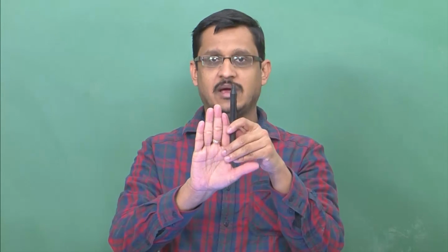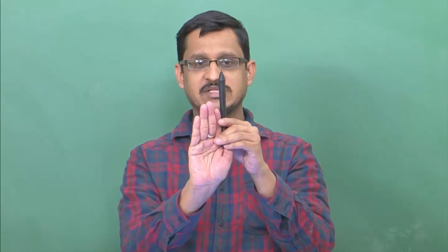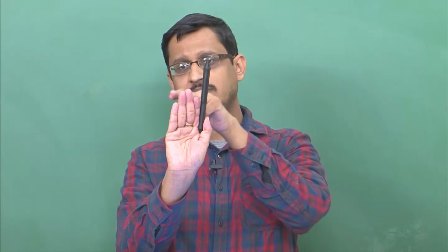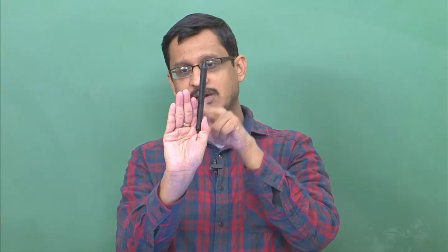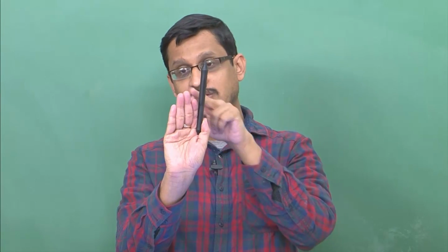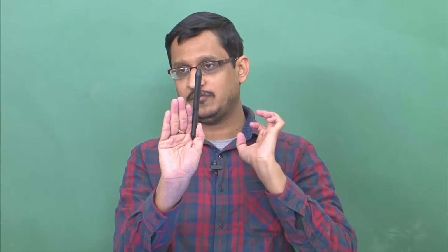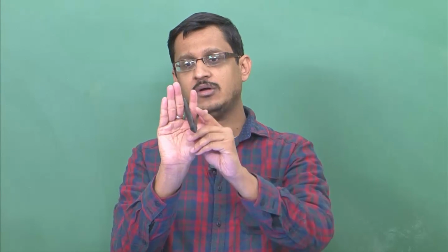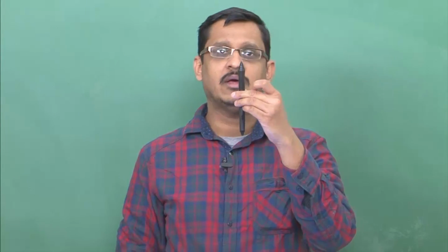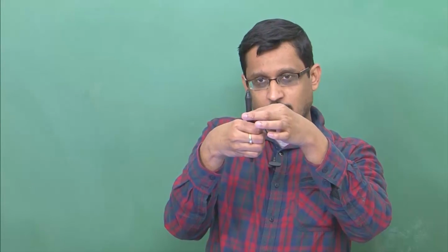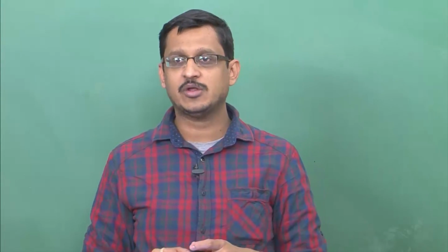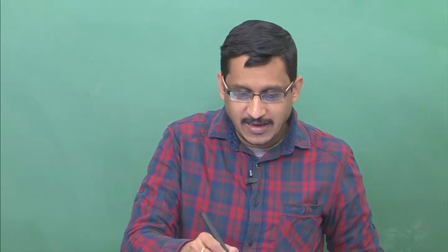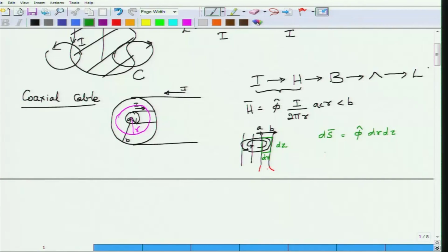So you have to imagine, I am not properly showing this one, but you have to imagine that there is an inner conductor and then there is an outer conductor over here, and I am considering the circuit between these points. Okay. So in this region there will be a magnetic field, and the magnetic fields are all going around the phi direction, right. So for this conductor the magnetic field lines are all curling around, and then if you actually cut open that coaxial cable, you will see the magnetic field in this region, so let me redraw that region for you.